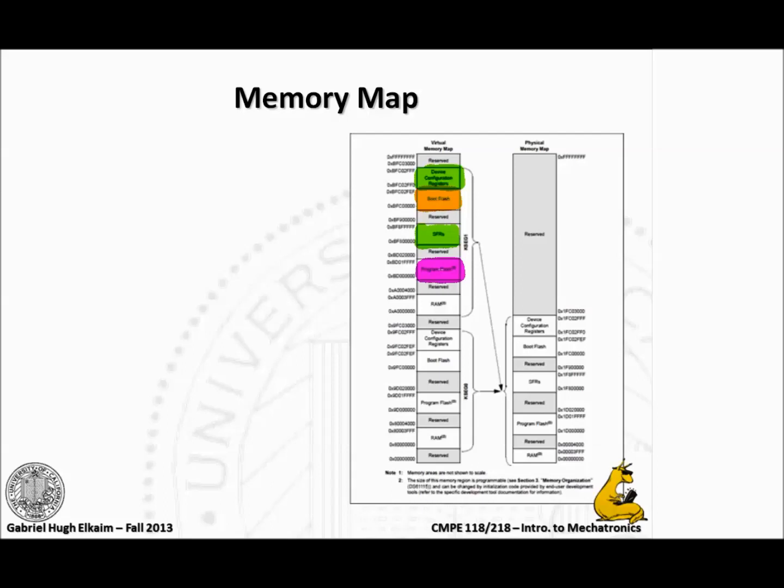Anyway, on the PICs, I believe we've got 32K of RAM. And at first, if you're used to a desktop machine that has 8 gigs, you're like, oh, good God, that's nothing. But for a microcontroller, this is very generous. Oftentimes, I've had microcontrollers that have 256 bytes of RAM, and that's all you've got. So you're not loading any large arrays in when you do that. And so 32K is generous.